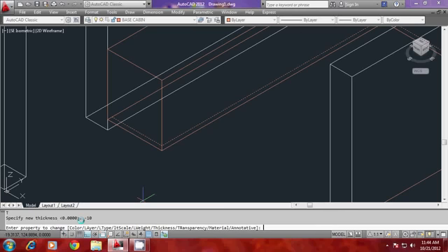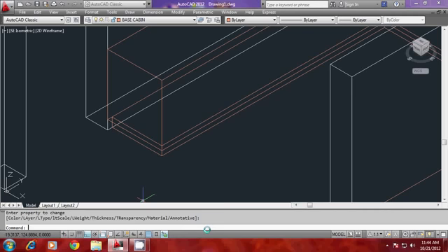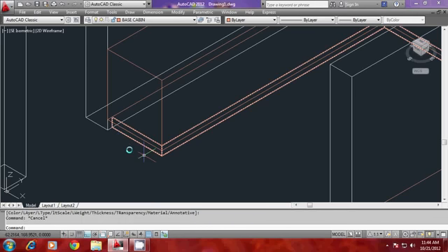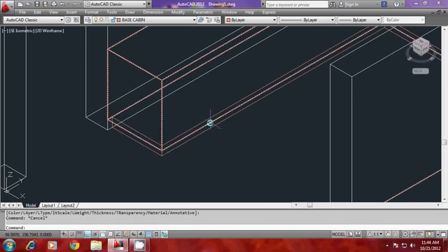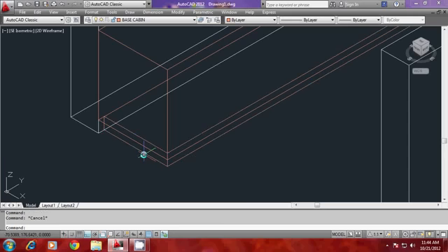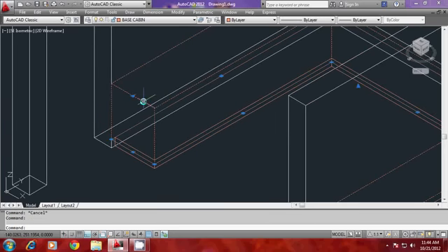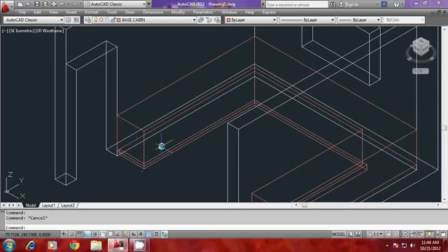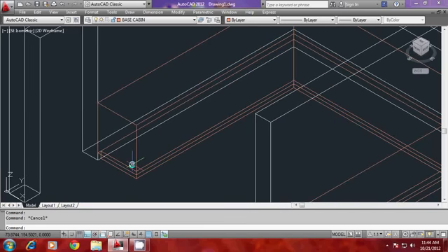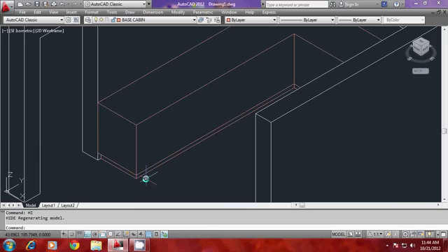Again you will come back to the property options, just give one more additional enter to go out of this command. Now you have just created a surface to simulate the skirting. So this is a perfect surface model, whereas this particular cabin is a solid model. So you can actually go for a combination of change property command and extrude command as and when required. It is a hidden representation. Now you can see the cabinet over here.